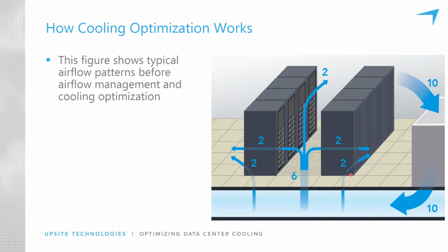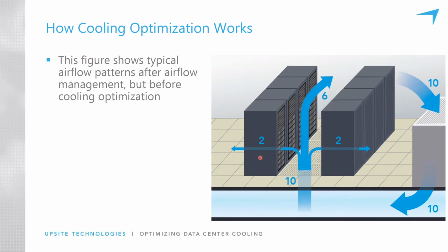So obviously we want to seal these bypass openings, right? We want to block this bypass airflow. Absolutely. And do you think that if we seal these openings and block these 2 units and these 2 units of air, here's a question to answer: will that affect how much bypass airflow is in the room? It's a trick question, kind of. The answer is, well, yes, it limits the amount of bypass airflow coming out of the raised floor underneath cabinets, but it doesn't change the amount of bypass airflow in the room.